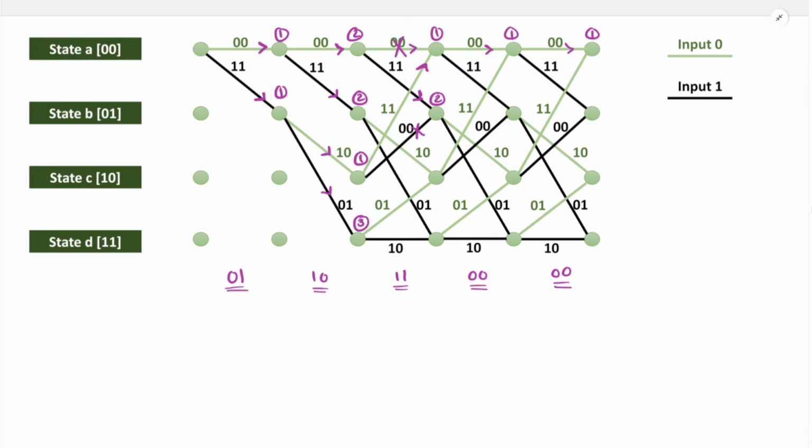If you identify other weightage, obviously that will be higher than 1. The reason is as you go in this direction with the other link, there will be higher weightage. So you'll have to ignore all other paths. Only follow the path that has weightage 1 over here. So let me show you the path. See this path that is having weightage 1 and other paths that have more than 1 weightage. So the Hamming distance with this path is 1, right?